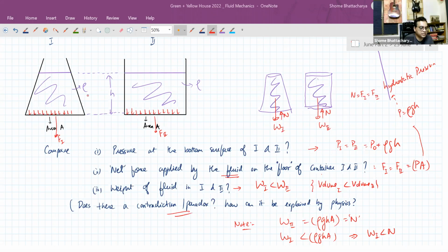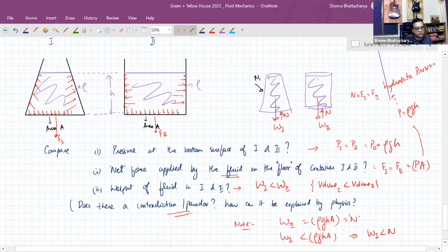Yes, very good, Yash. That's correct. Yash Bhavishkar. The explanation is correct. So what happens here is that the force due to the liquid acting on the side walls is like this over here. And notice that the force is increasing because the pressure is increasing. But here the force, because of the liquid on the side walls, they are upwards. So now when you consider the liquid body, it experiences a reactionary force because of the walls, like this. So here the side walls are applying reactionary forces like this, which creates a net downward force. Whereas here the side walls are creating reactionary force like this.